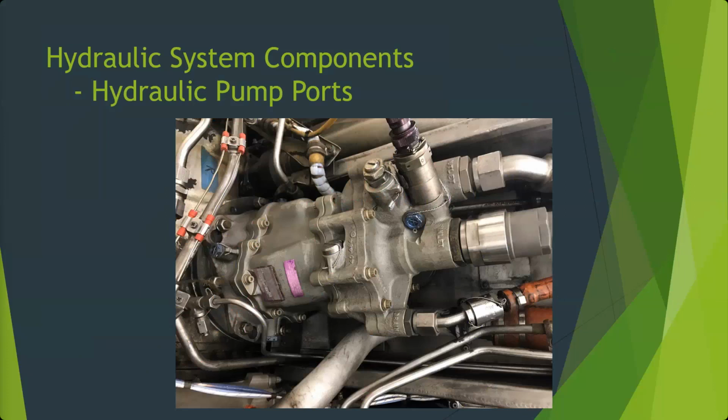There's a seal inside here at the shaft. So there's no fluid in this area, or there shouldn't be. If there's fluid in this area, it's actually designed to leak out, so it shows the seal's leaking. And if you get fluid in this area, you got to see if it's Skydrol, the pump's leaking. If it's oil, the engine's leaking. If it's Skydrol, the pump's leaking, and soon the engine's going to leak because the seals on the engine don't like Skydrol. So you may as well replace both of them when you pull the pump off.